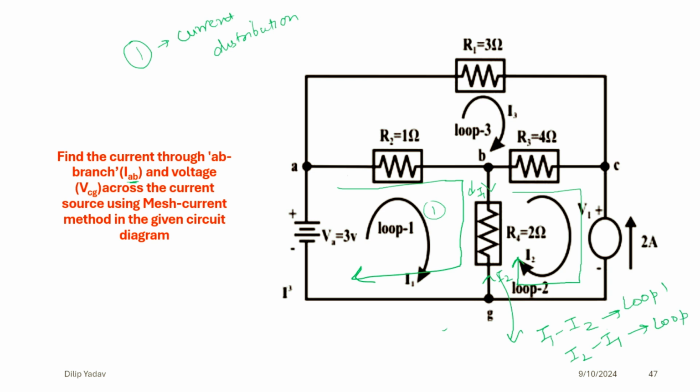So if now we have I3, and this we said is the current that is flowing into the circuit, that is I3. So across R2, if I need to find out the current across R2, this was the current I1, and again the current coming at this point is I3. So when we are taking the loop, the current across R2 will be I1 minus I3.